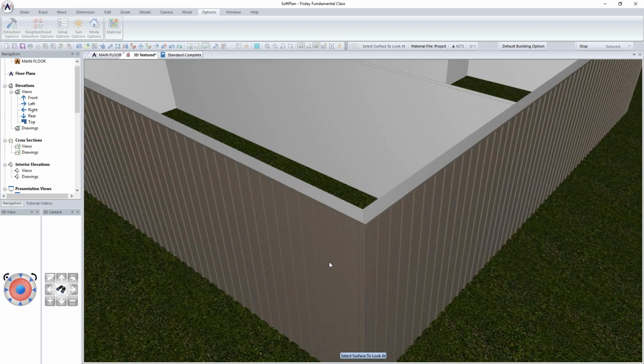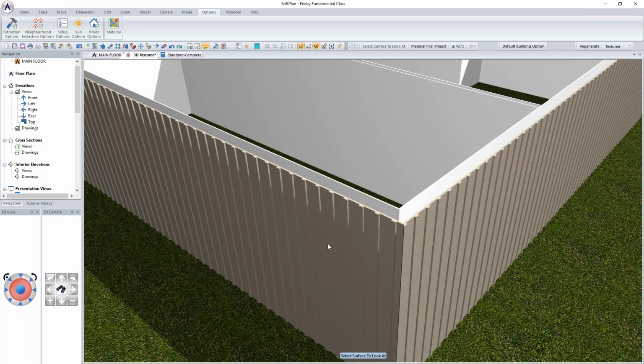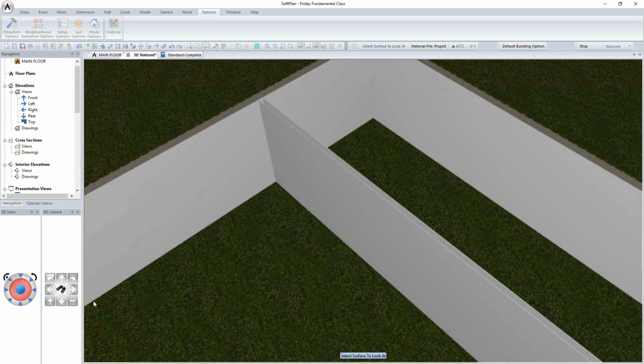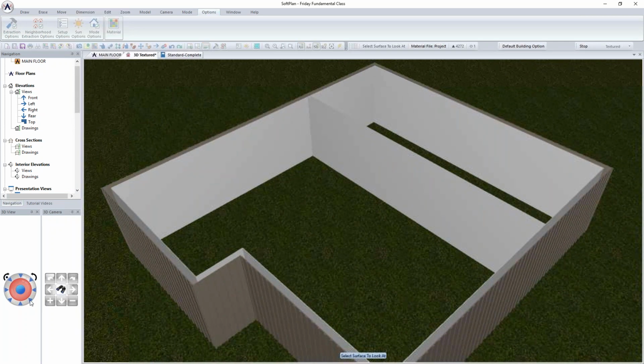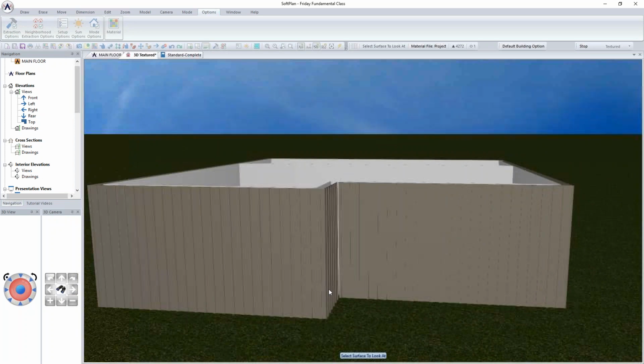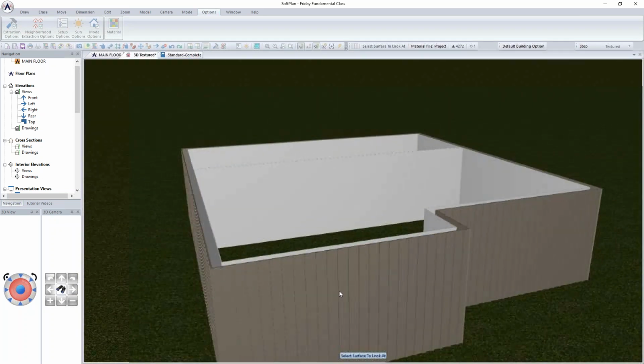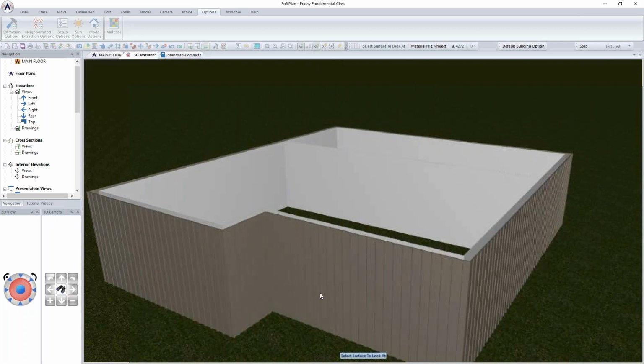Once you've done that, you can then hold down the mouse wheel and you can orbit the model per se on the plan. And so I just hit this triangle here to get out to this 45, then holding down the mouse wheel, I can then move my mouse around to orbit this plan and see what I want to see.